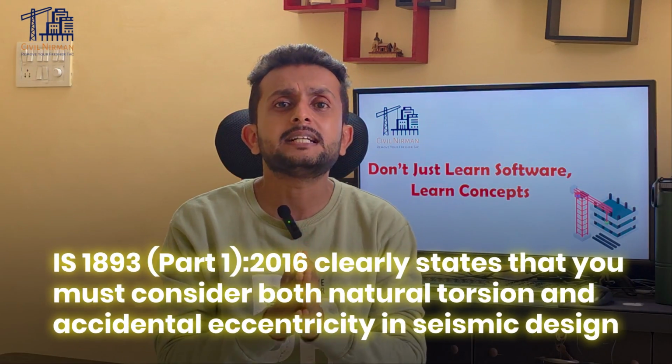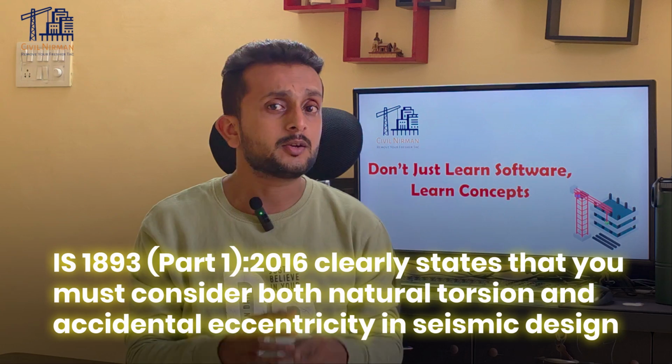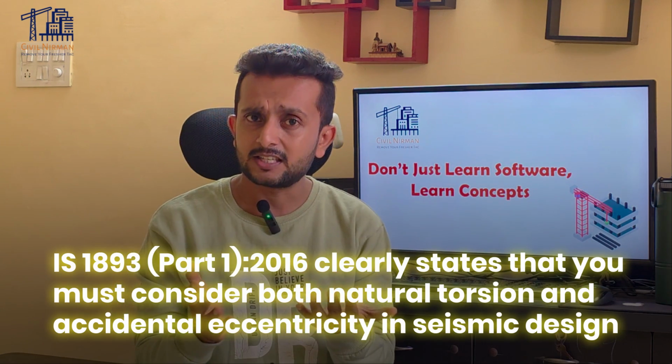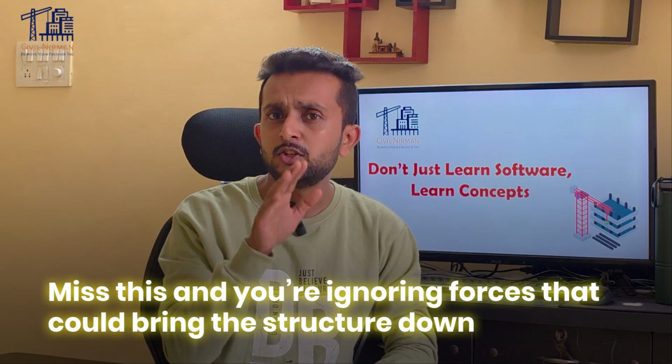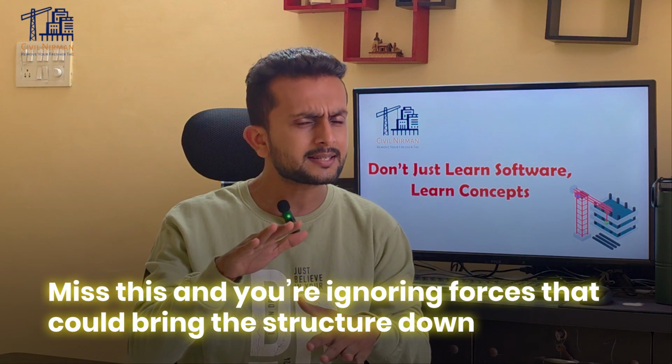IS 1893-2016 clearly states that you must consider both natural torsion and accidental eccentricity in the seismic design. Miss this and you are ignoring the forces that could bring the structure down. So let's understand the solution. Let's go to the code.